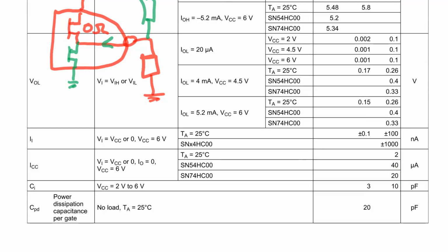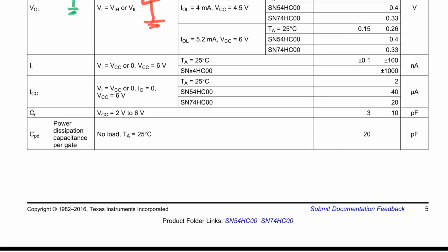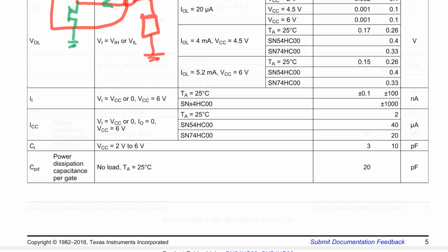That's, geez, fly halfway to the moon on 20 microamps. Anyway, let's continue. But that 20 microamps is actually over the full temperature range. At the ambient temperature of 25 degrees, you'll notice that it's only 2. So it's an order of magnitude better than the banner spec right up the top. If you just took that banner spec, yeah, that's worst case over the temperature range, but you're not going to be using your product at minus 40 degrees, for example, or right up at plus 85.